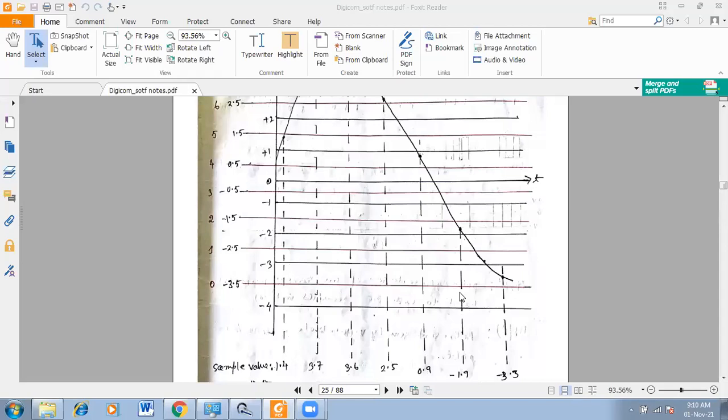So whatever be the peak to peak amplitude, that signal strength must be quantized by means of a few constant number of levels. That is called quantization level. Okay, here we are going to use 8 number of quantization level, and it is always a power of 2.